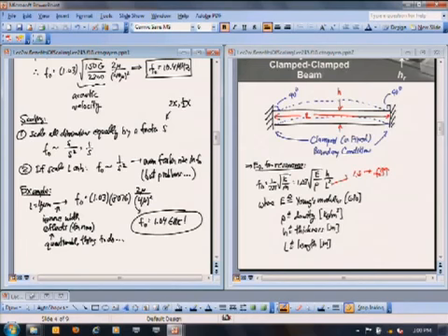Yes? That frequency equation, is that still valid for such a large aspect? No, it's not. That's why I wrote this questionable thing to do. Because when your width is that much larger, actually your thickness too, there's width, there's thickness, there's all sorts of different effects that go into this. The solution becomes much more difficult. And we've certainly worked it out, and there are papers out there that talk about the exact solution. But yeah, you would not end up with this dimension at 1.04 gigahertz.